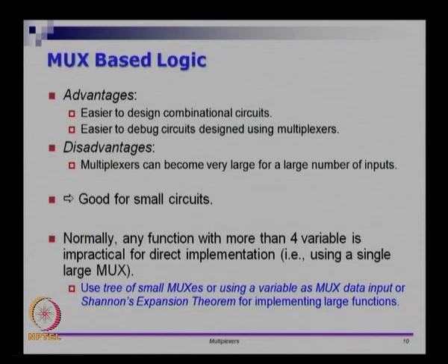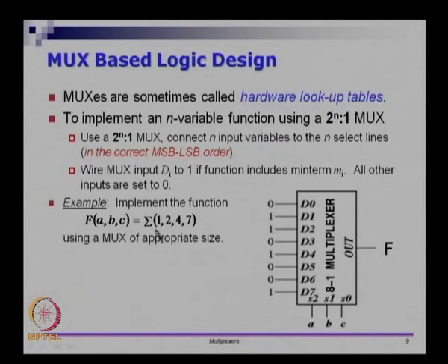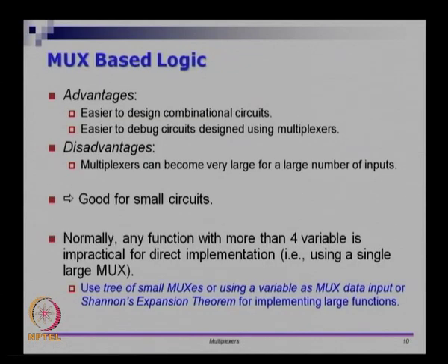However, it comes with a disadvantage. The problem is that muxes can become very large for a large number of inputs. In this case, we didn't do any minimization. There may be some structure to the problem here, but we didn't see any structure, we didn't minimize anything, we just stuck the truth table here. So the circuit may get very complicated. You may actually spend more to do simple functions even. So mux based design is okay for very small circuits, it's not good for larger circuits.